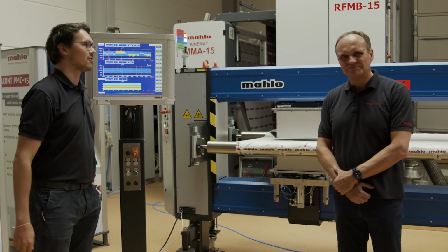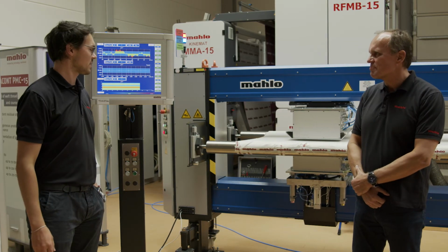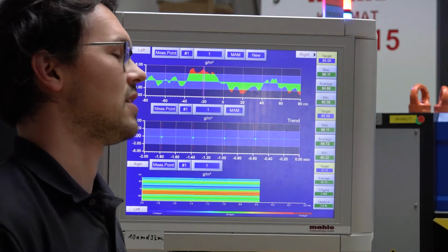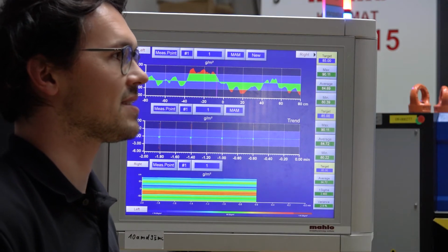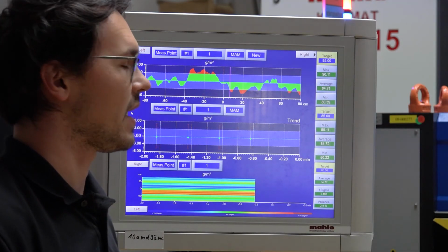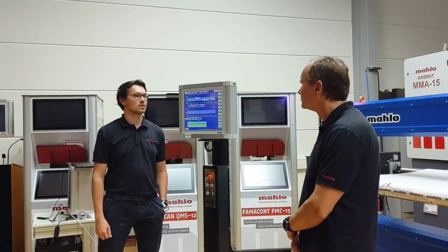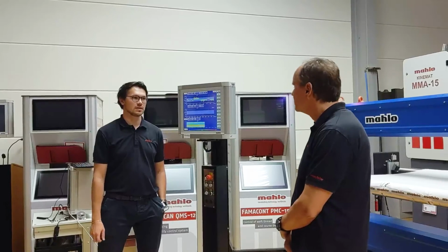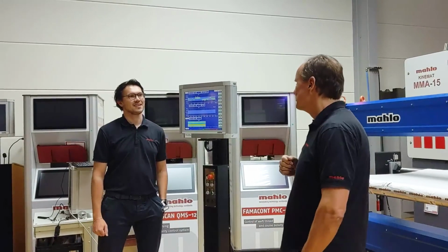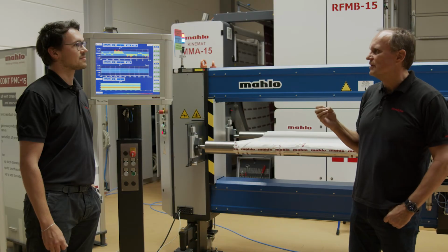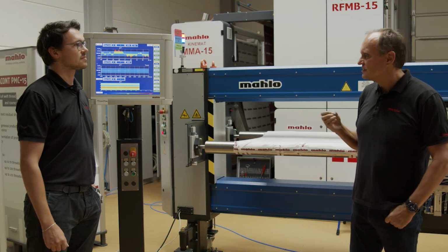Today I'm using our QMS gauging system for measuring some basis weight of non-woven products. Customer request: a sample testing report will be made afterwards. And today I'm using our FMX X-ray based sensor. So this is the X-ray system that runs without license and